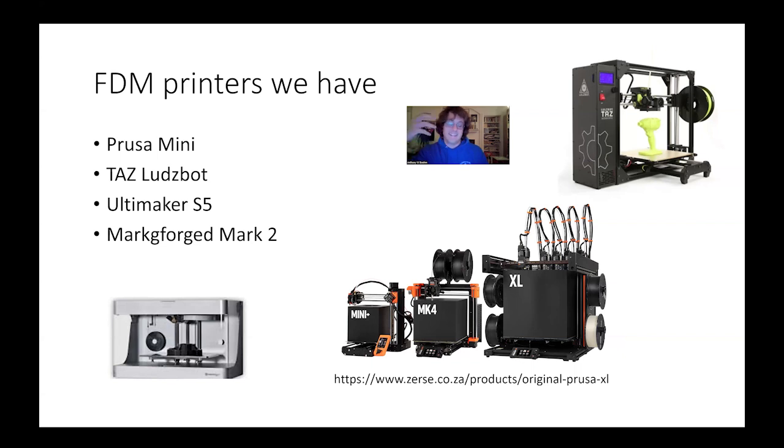Okay. And in addition to the filament being tough, you have the ability with this machine, in a different extruder, so dual extrusion, I guess you can't really call it extruding because it's not melting anything, but it's able to feed in carbon fiber, which allows you to lay in continuous strands on different planes, which is much stronger than just having little flecks of carbon fiber that are non-continuous. Okay. So pretty cool capabilities in our machines. There are a couple of other ones floating around, but these are the main FDM printers that we have.